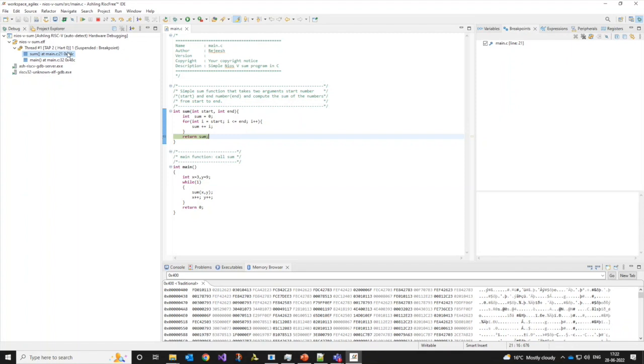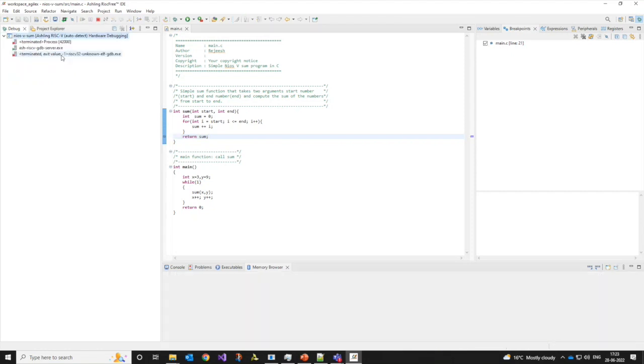Now phase two. Instead of using this application, which is already bundled with RiscFree, we have the tools coming with Quartus, using which we can create BSPs and applications for the Nios cores. What I'm going to do is debug such an application, which is created using these Quartus tools. So I'm just going to terminate the session, stop debugging, and remove everything.